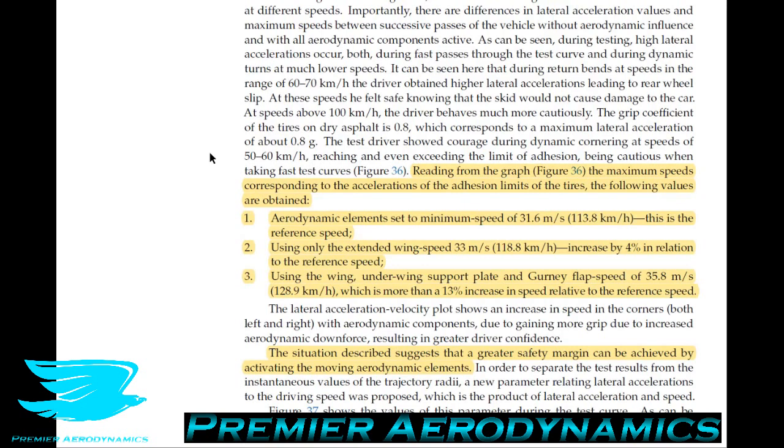So the aerodynamic elements set to the minimum speed of 31.6 meters per second. So this was for the minimum aero setup. They could only achieve this speed of 31.6 meters per second.